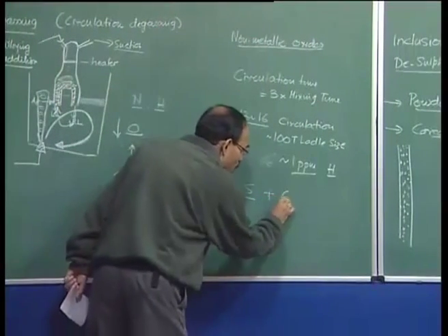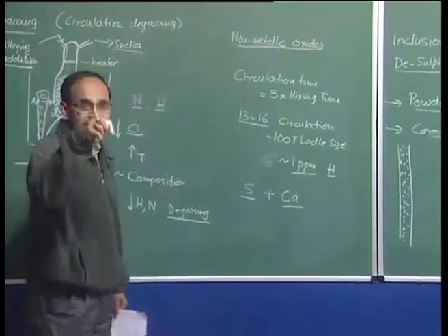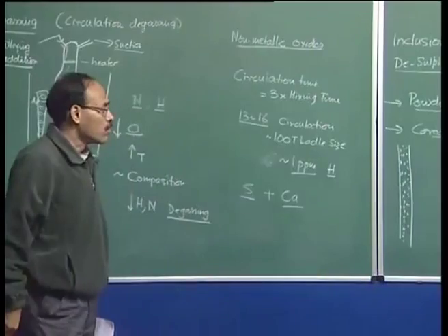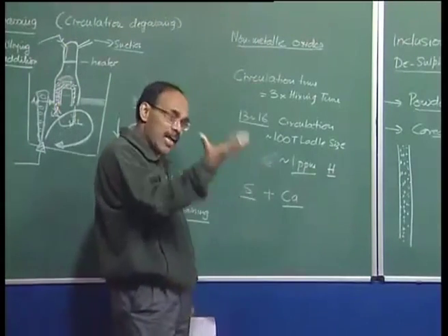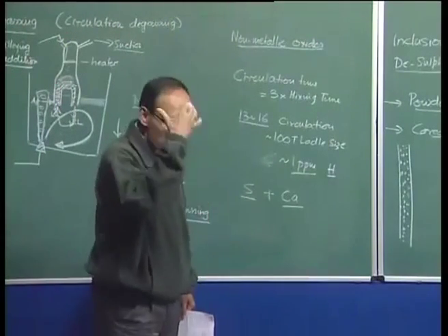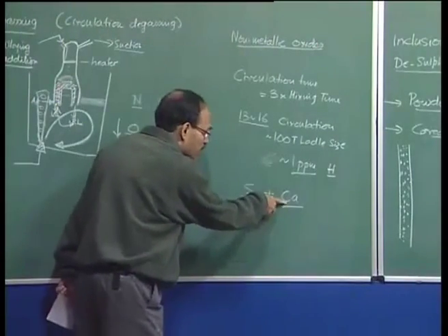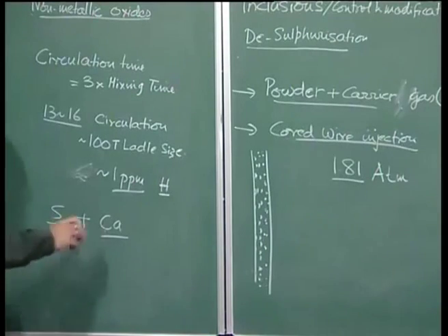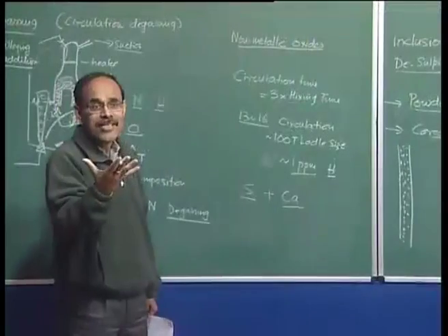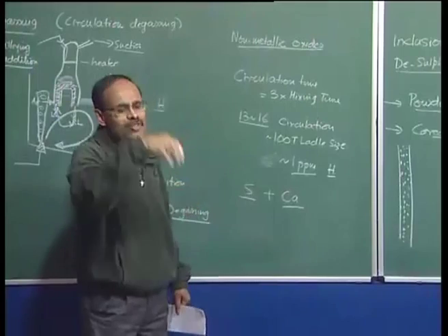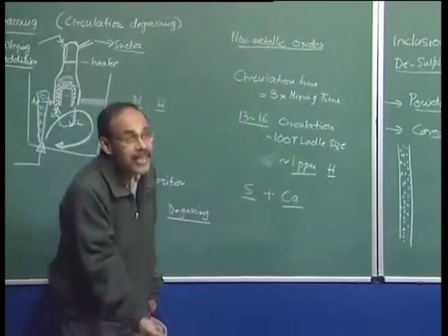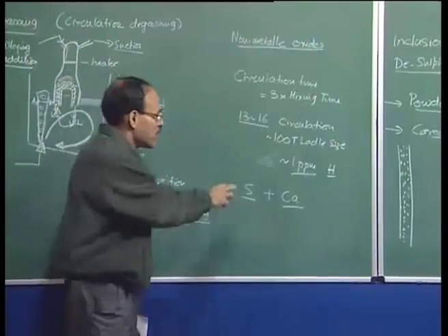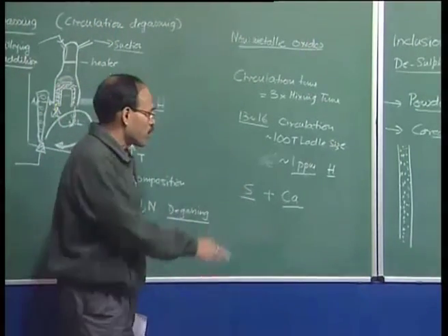The calcium from the powder has to get into the state of dissolution. The calcium powder has to melt and dissolve; even if it becomes gas, it has to dissolve into steel, and only then is the sulfur atom going to be accessible to it. But this dissolution will depend on how much contact time there is. If the injected calcium does not stay there for a long time and immediately surfaces in the form of big gas envelopes or bubbles, we can understand that there is virtually little scope for calcium to get dissolved.